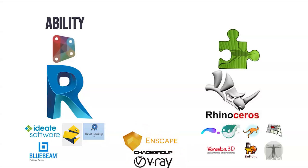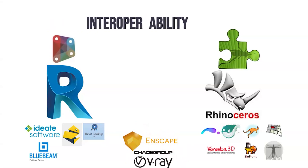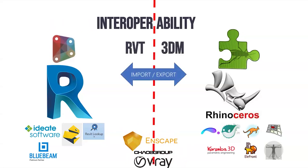When transferring a design from Rhino to Revit, the workflow usually involves importing a 3DM into Revit, 3DM being the Rhino native file type. However, it will come in as a generic model. It will not be categorized properly, and won't section as native Revit walls and floors would. So the workflow requires a lot of wall by face commands, and generally a lot of rework is necessary to make the two play nice together. Until now.